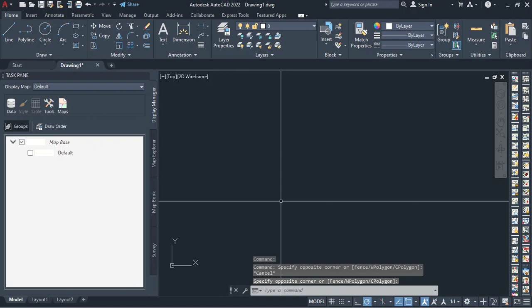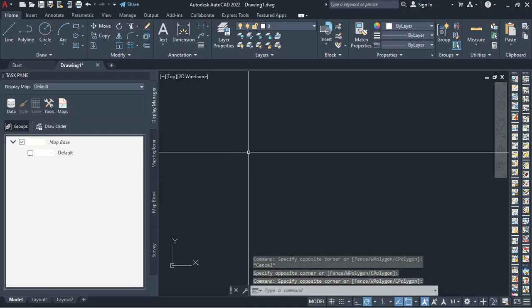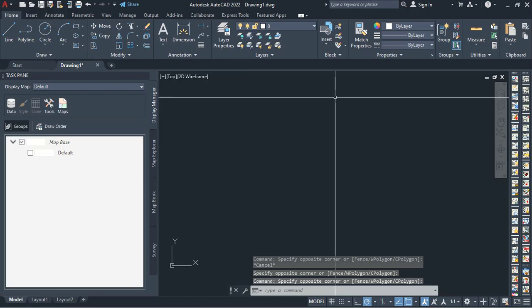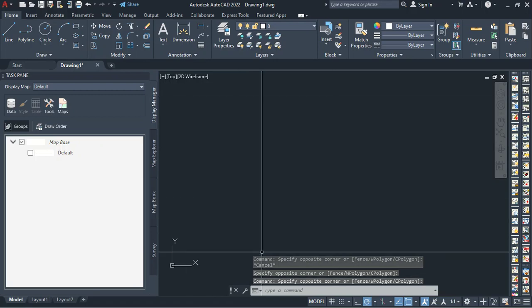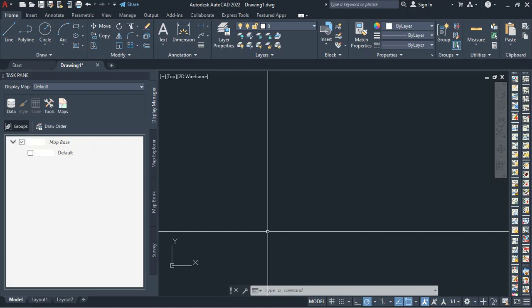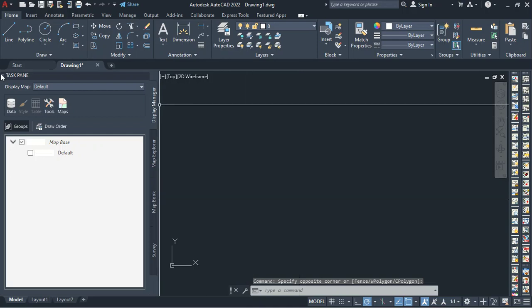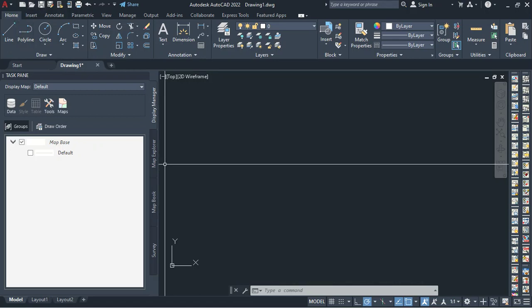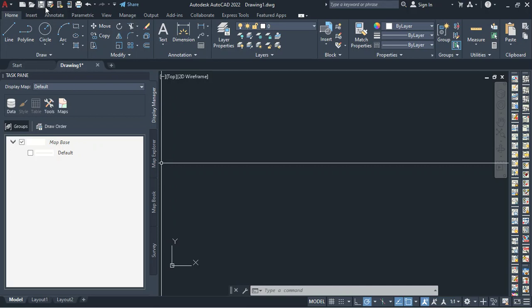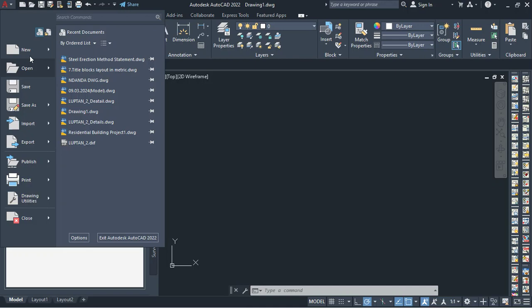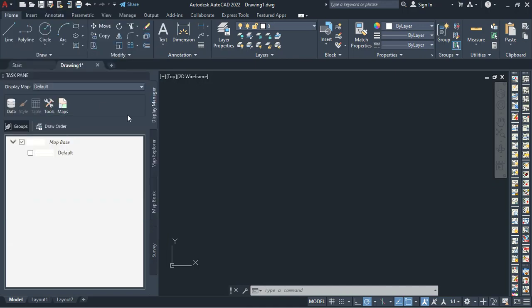Now, after opening AutoCAD, of course, we have to prepare the structural layout from the architectural plan. And I shared the architectural layout that we are going to use. It's just a very simple plan to help us understand how to prepare the structural layout, and how to perform design in AutoCAD, in ETABS and ProtaStructure. So in the structural layout, this is what we're going to do. From the architectural plan, you have to create the grid lines using the AutoCAD line command. So for this one, first of all, as we open AutoCAD, I just saved and set my units. Then the next thing is to create the layers.